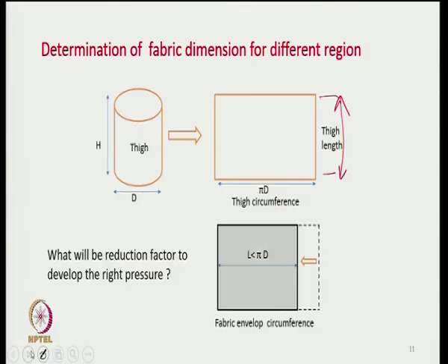In that case, this is what the situation is going to be, and if this is the actual thigh circumference and thigh length, the fabric envelope that we will require will definitely be shorter than this, because we need a certain amount of stretch to develop. So, fabric length L has to be less than pi d.